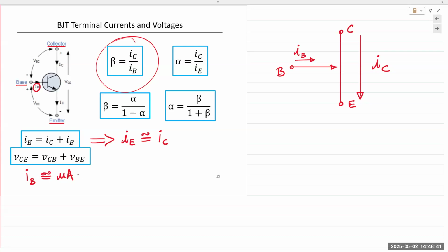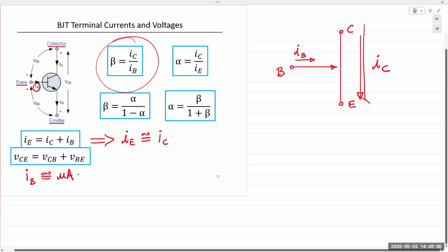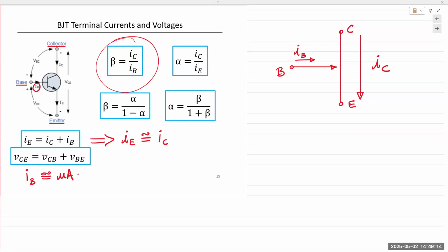Now, the external voltage is fixed. VCC, if you apply 5 volts, is fixed at 5 volts. If you apply 10 volts, it's fixed at 10 volts. So if you don't do anything other than apply a DC voltage, you have a fixed amount of current flowing from top to bottom, from the collector to the emitter. We can't change the value of that current. Once you fix VCC and the resistors in the circuit, the collector current is fixed, a constant line.